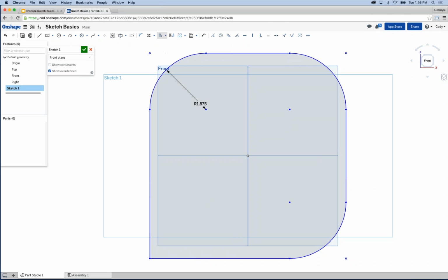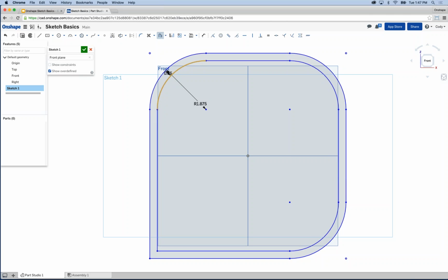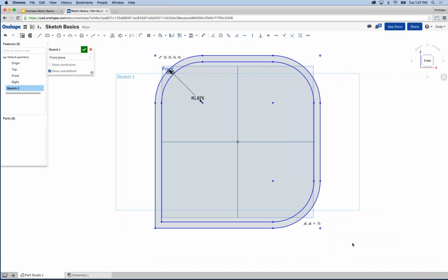I don't want to sit there and left click all the individual entities one at a time. So I can select offset, and instead of left clicking individual pieces, again, use that left click drag. If I left click drag, it will automatically offset the entire chain of sketch entities instead of just the individual piece. So very useful if you have a lot of sketch geometry you want to offset at once. You don't have to left click each piece; left click and drag, and you get an offset of the entire chain. So that is, again, just a tip on the offset command.